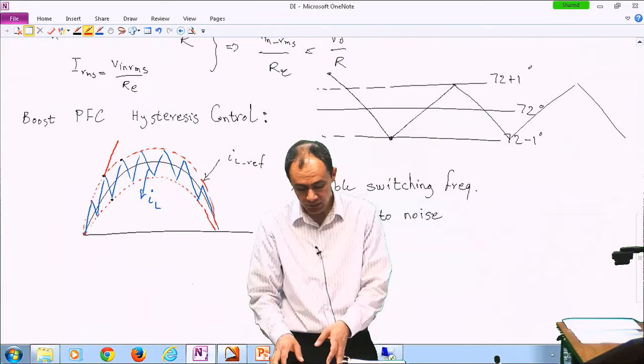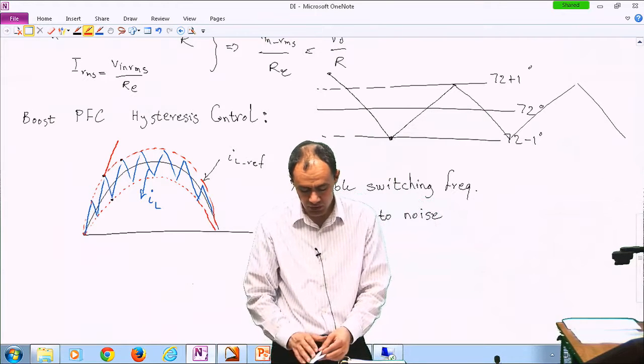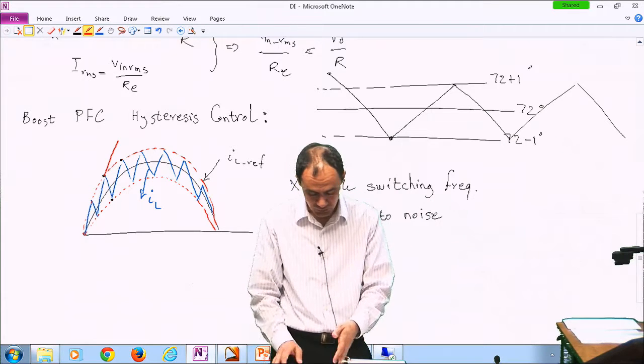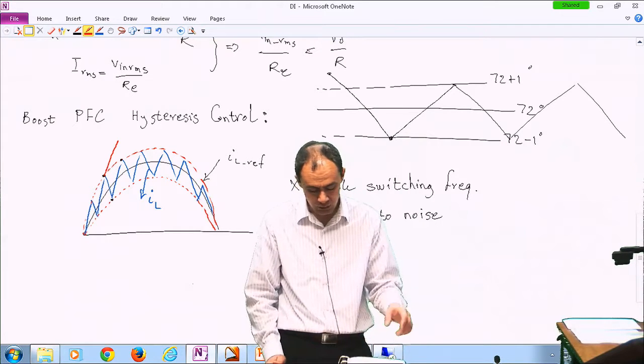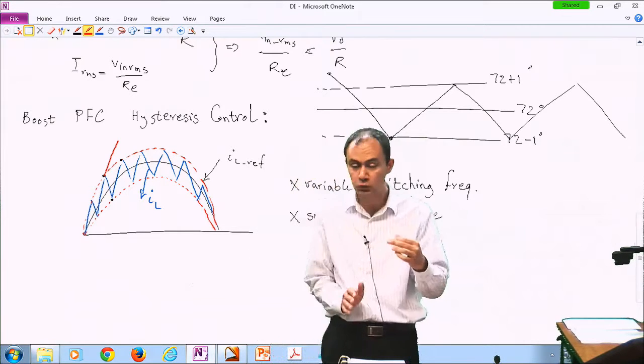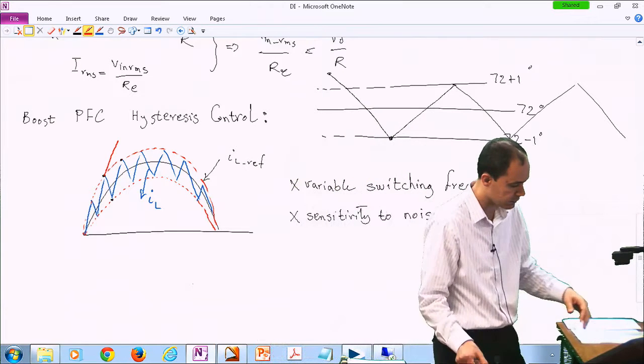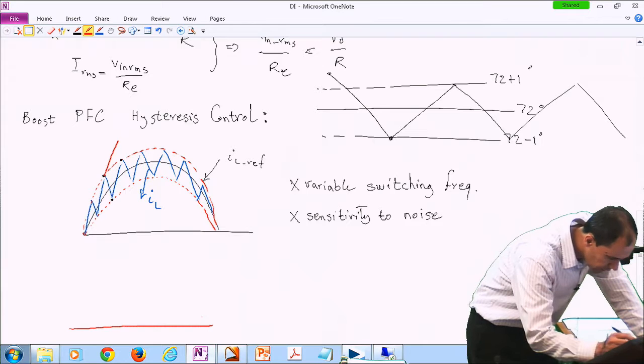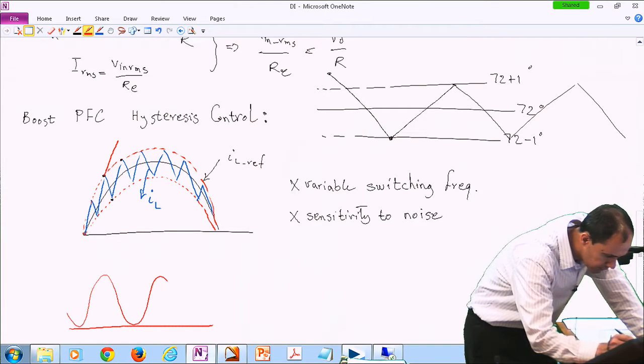Ultimately, you're trying to control the waveform of your input current. And there are lots of approaches other than the boost and the flyback, like for instance using the SEPIC converter or Cuk converter, and paralleling, putting two converters in parallel. So one common approach is, for instance, if you remember, we drew the input power with something like this.